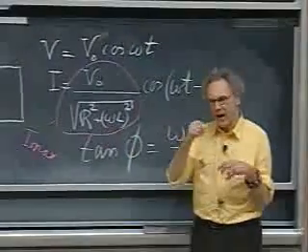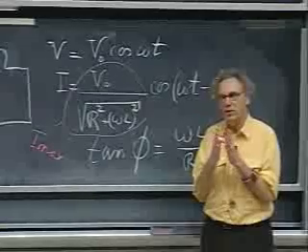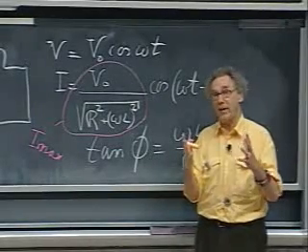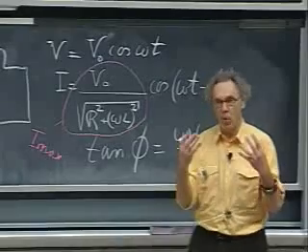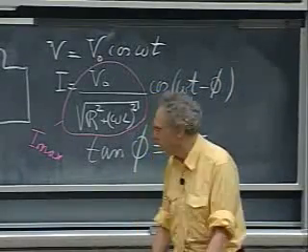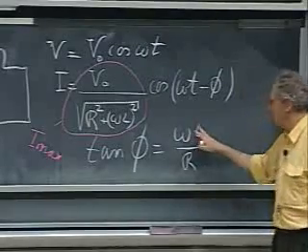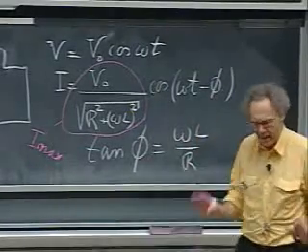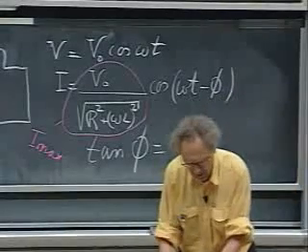If omega is high, then the time changes occur on a very small time scale, and so the system can fight back. Because remember, you always have the EMF proportional to di/dt. And so it's also pleasing to see that omega and L are upstairs here. For either one of them being large, it can fight back and it can hold back the current.